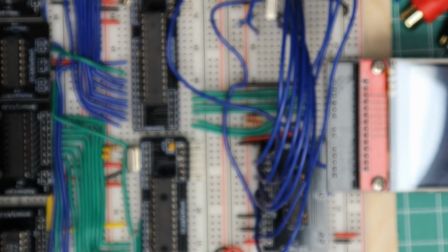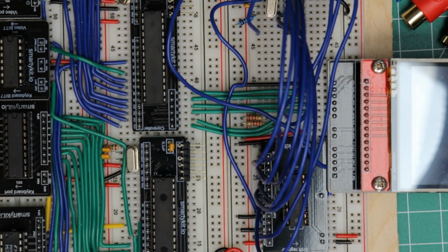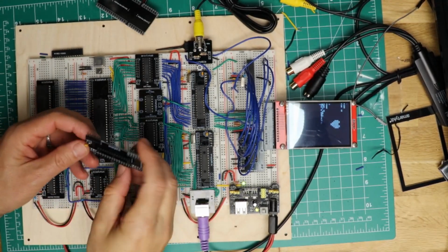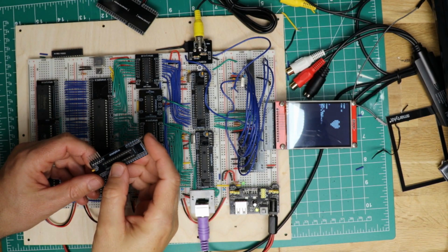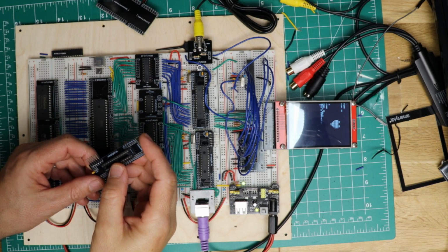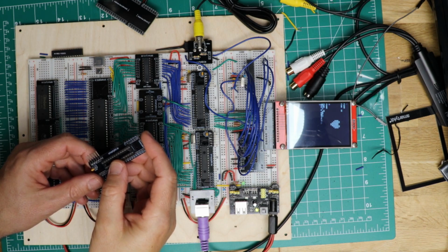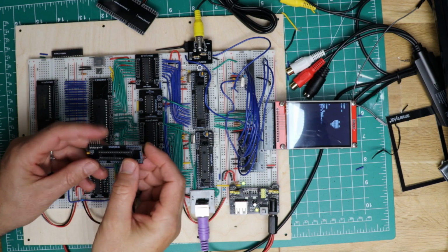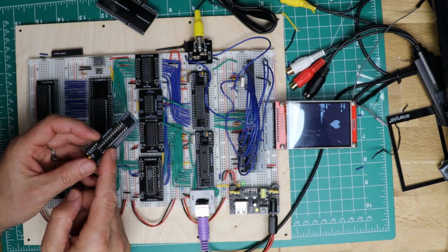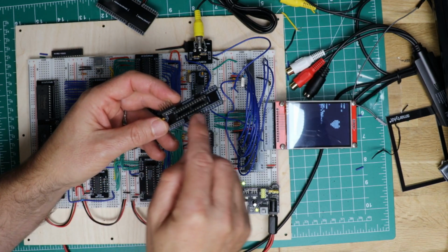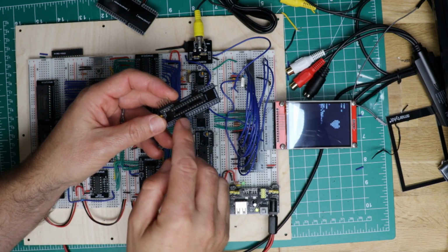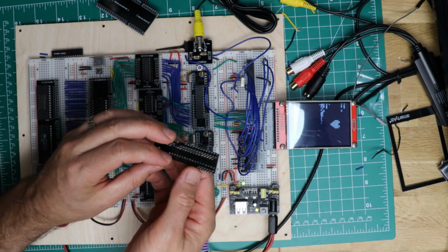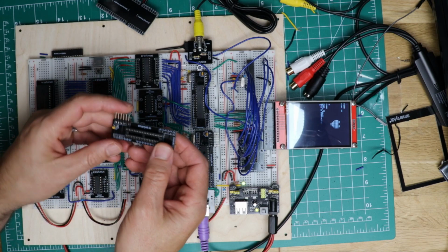Which is a bit odd. I don't know why it's done that way, because if you're going to mass produce these things, you're not going to CNC them. It just takes way too long. You would get them etched properly. So I don't know what process they used for that, or why they've done it that way. But it might be that the tolerances aren't good enough and there is a manufacturing problem there, or there's a track that runs through. I've done this before, where I've routed a track through a pin that it shouldn't go through, and I haven't checked the DRC. But yeah, it's a bit strange.